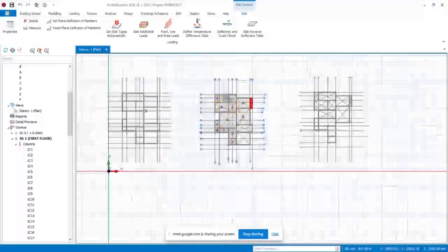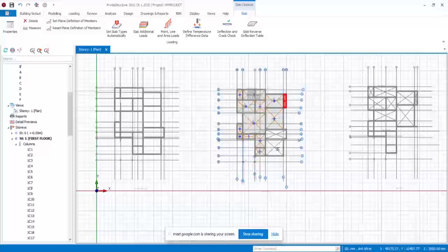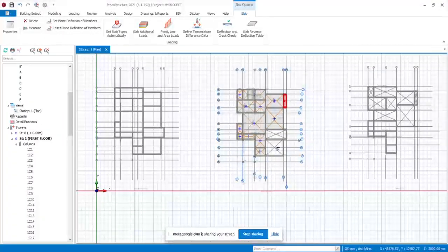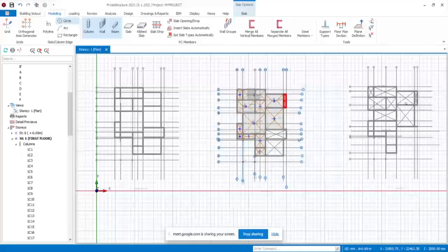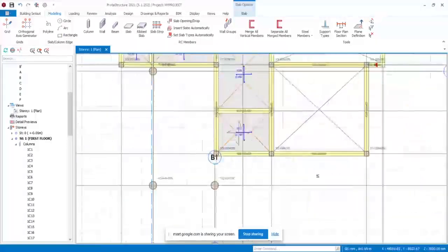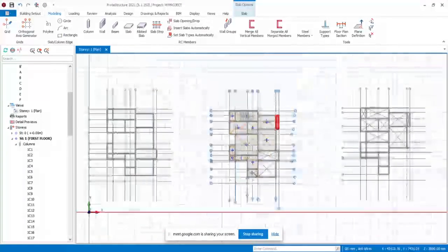Now we import three GAs together. Let's now do the roof GA, the roof arrangement. Then we'll see how it looks in 3D, and we can begin some other settings. Now I want to move this GA to be in alignment with where we are working because this roof is supposed to sit on the first floor. So we want to move that to that place to see how we can proceed.